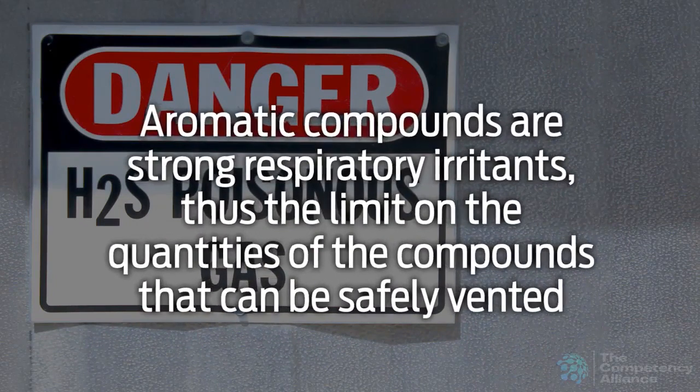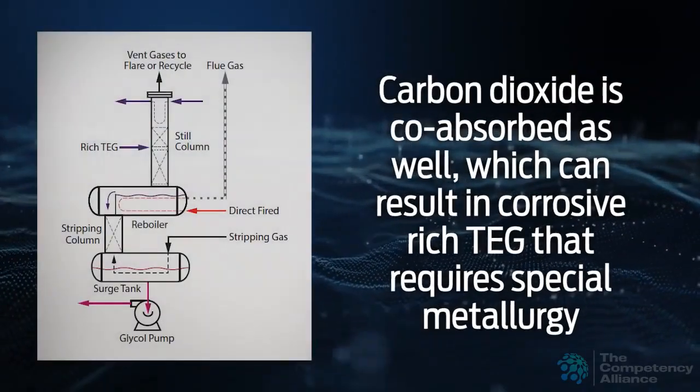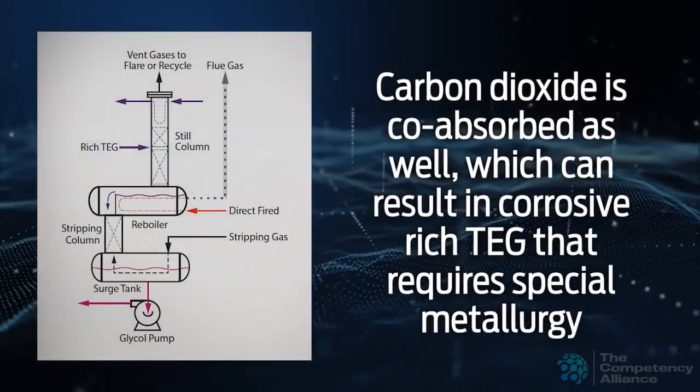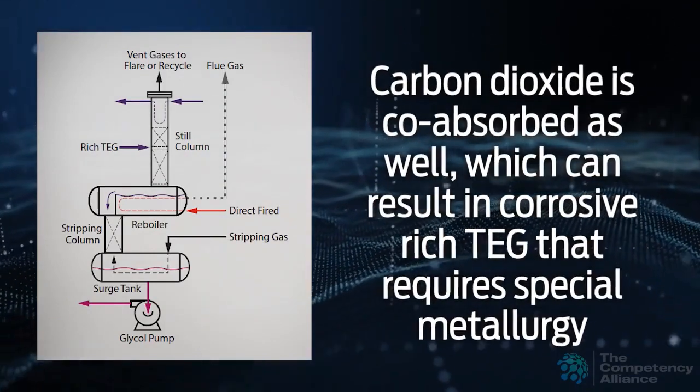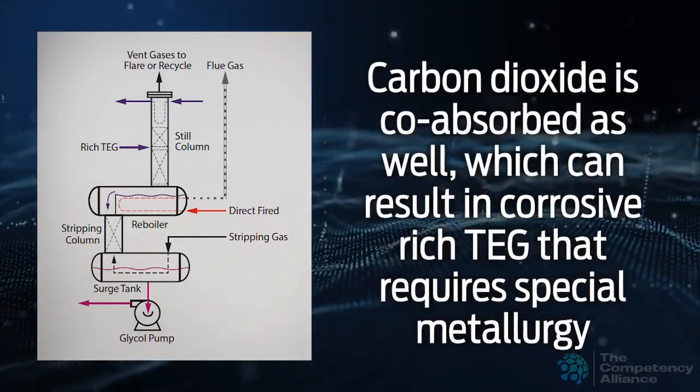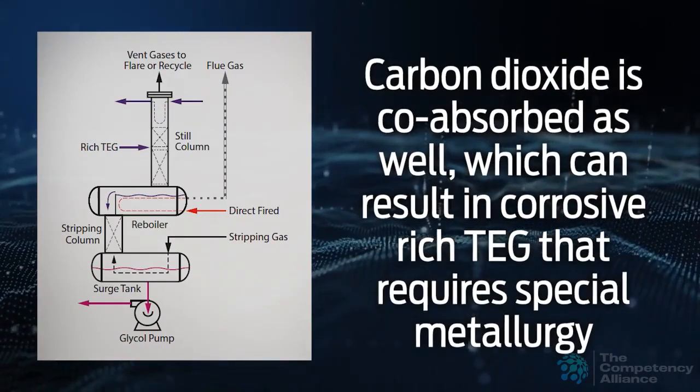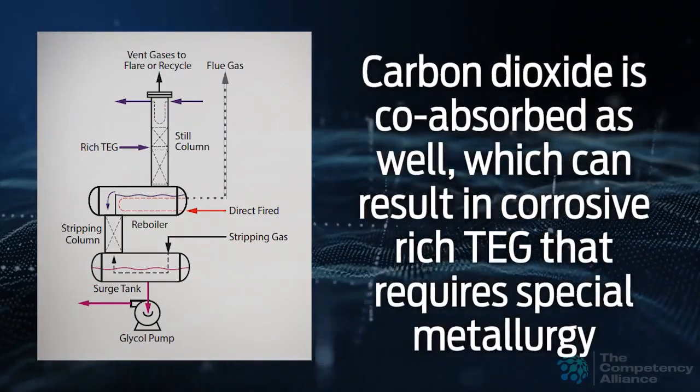Carbon dioxide is co-absorbed as well, and at high inlet gas concentrations and high contactor operating pressures, this can result in corrosive, rich TEG that requires special metallurgy.